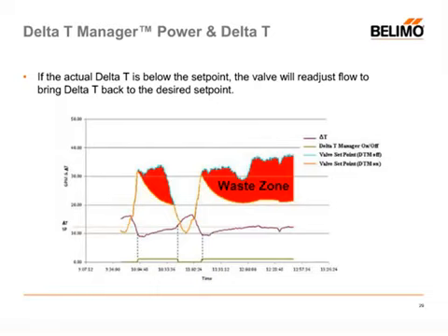And let's look right here. Let's say this line running down at the bottom is 20 GPM. So we have about 20 GPM of flow that was running through that valve over a 2-hour period. So that's 20 GPM over a 2-hour period, which is 2,400 gallons of wasted flow that went into the waste zone. That coil could have produced the same amount of heat exchange with 2,400 gallons less. Now, if you multiply that times a typical 5-day work week, that's over 10,000 gallons of flow that went through that valve over a 1-week period. That's a lot of wasted flow through a coil.